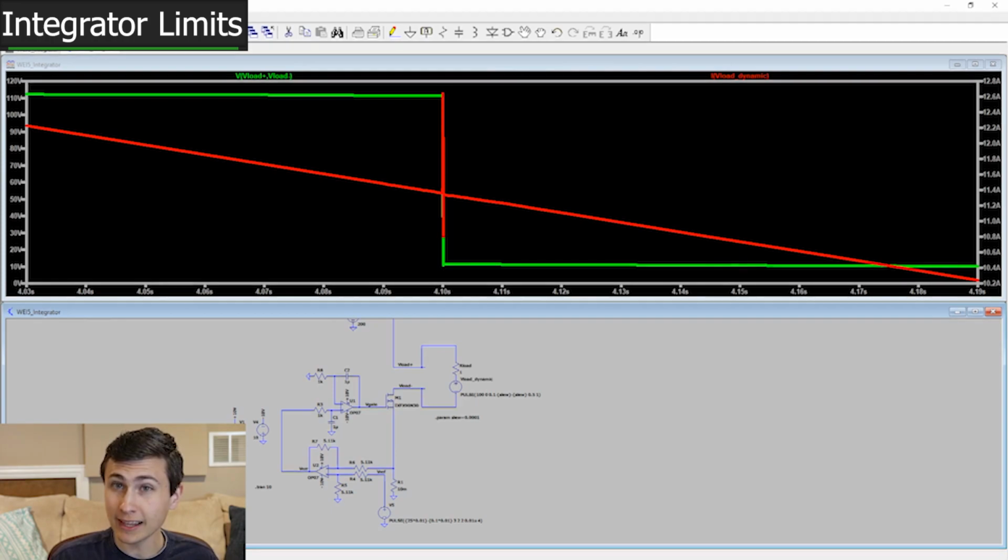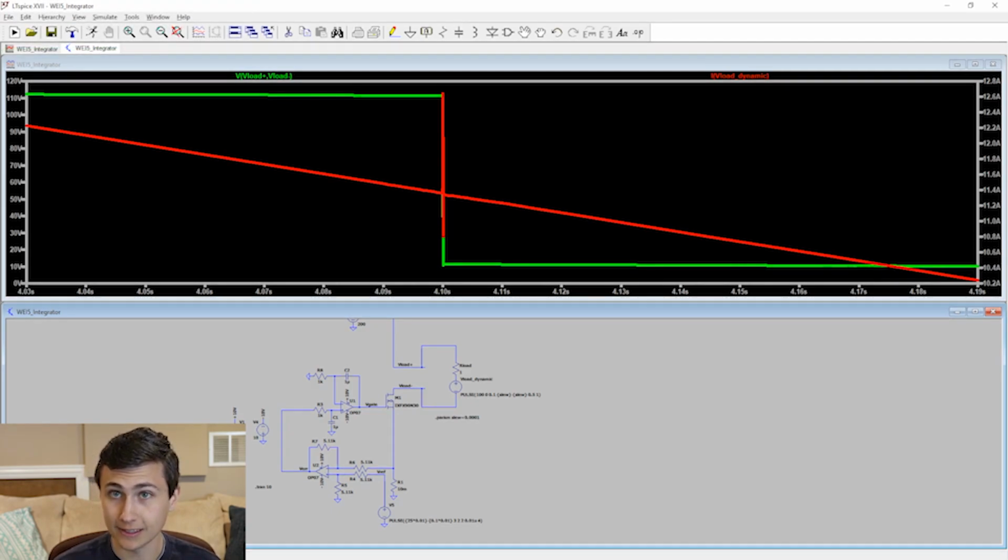And if we want to try to eliminate that, the D term can help to counter that by saying, hey, our current is going through the roof. Turn down that output voltage a lot. The D term is only there for a moment. During that transient, it goes away. The I term compensates for the steady state error again, and everything comes back to normal. But if we get our D term tuned just right, making this not just a simple I controller, we might be able to improve the transient performance a lot, make it a lot more stable, help it to accommodate things like this. But we can't cover that all today, so you're definitely going to want to stay tuned for our next video.